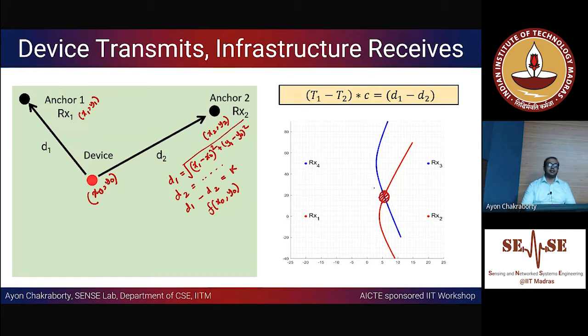And that is the reason I spoke about TDMA two or three slides back, right? That is how you are designing the MAC. The medium access control has to be designed accordingly. So you cannot allow multiple devices to range simultaneously. Whenever my device 1 is broadcasting, device 2 has to keep its mouth shut. So you have to enforce some medium access control such that not all of them talk simultaneously, otherwise it will interfere, and interference means it is just going to collide and nobody is going to hear anything.